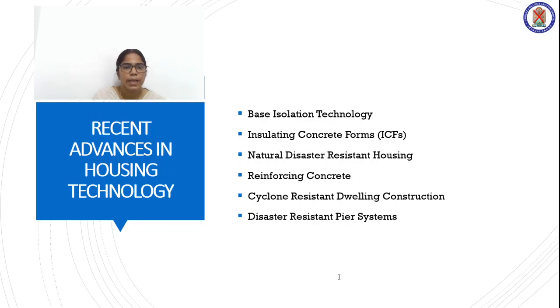And the next type is reinforcing concrete. The most widely accepted form of reinforcement is welded wire fabric, WWF. It is a mesh of thick steel wires that is placed in concrete. However, synthetic fiber reinforcement avoids the increased labor cost and difficulty in placement that are associated with WWF, and small diameter synthetic fibers are now being added to concrete in order to reduce shrinkage and cracking by more than 80%.